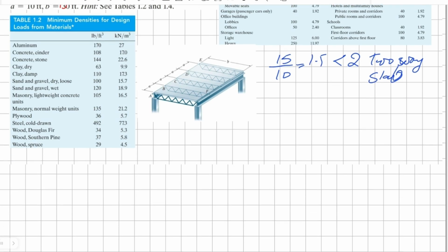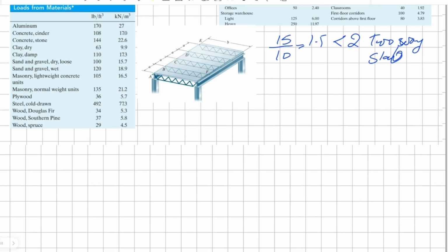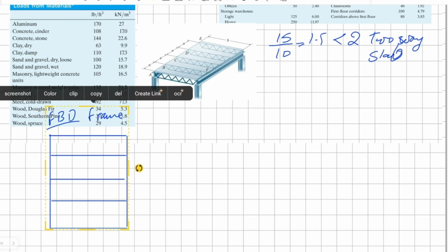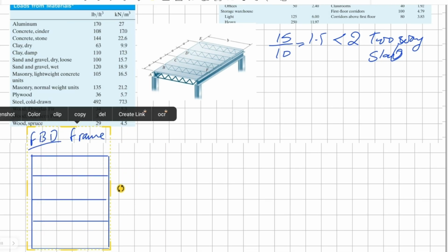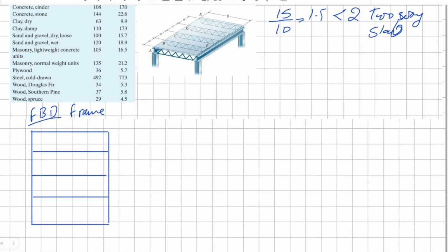Okay, before we proceed, let's draw the free body diagram of the whole structure. And from our lecture on tributary loading, we know that the loading for a two-way system is distributed in a triangular pattern towards the girder and then trapezoidally onto the joist.